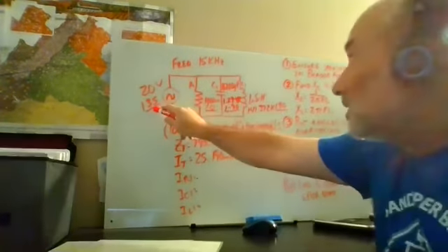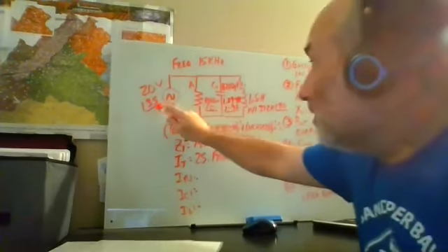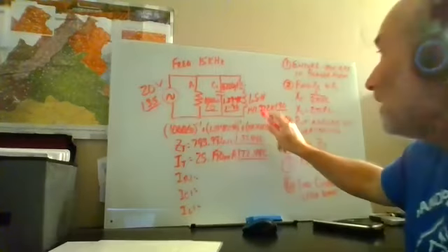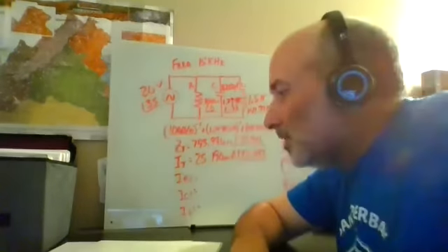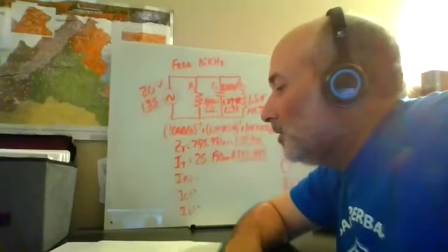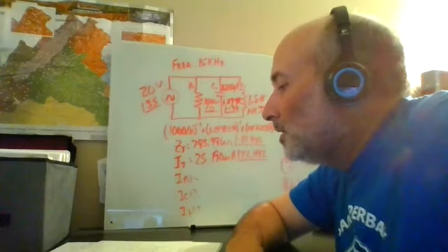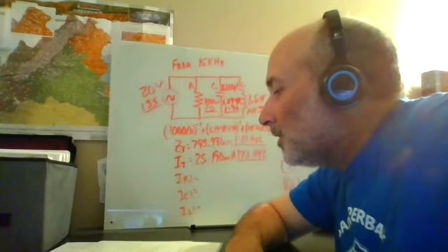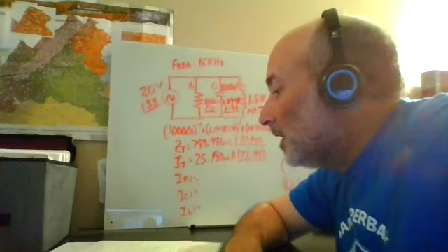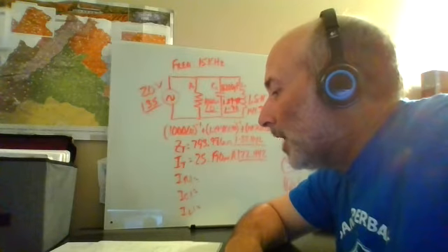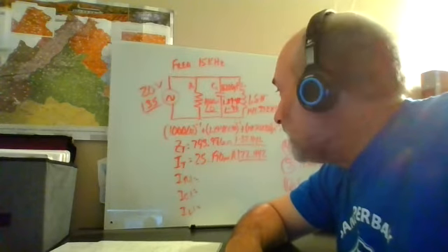So all I got to do is take the voltage divided by the impedance, voltage divided by the impedance, the voltage divided by the impedance, and I get the current through each one of my components. So again, I'm not going to write these all down because I know they're going to be hard to see, but I will tell you what they were. IR1, 20 milliamps at an angle 35. IC1, 15.456 milliamps at an angle of 125. And IL1, 141.471 microamps at an angle of negative 55.